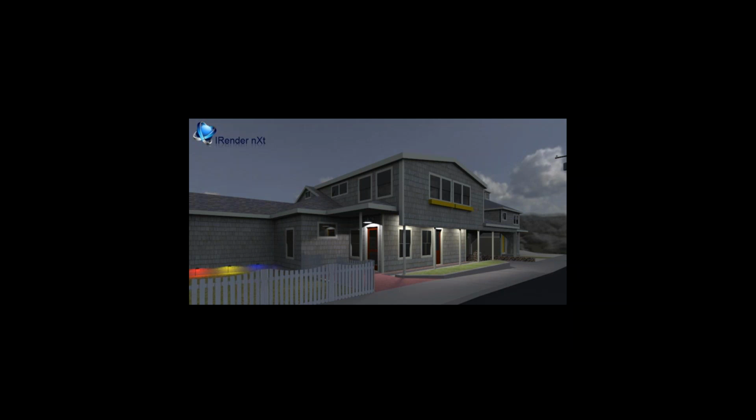Next, I used the lighting channels interface to turn off the sun, lower the brightness of the sky, and then flip on the artificial lighting that I had added to my model. And now, from one completed rendering, I have an additional rendering that I can take to my meeting, showing an evening view of this model with the lighting.